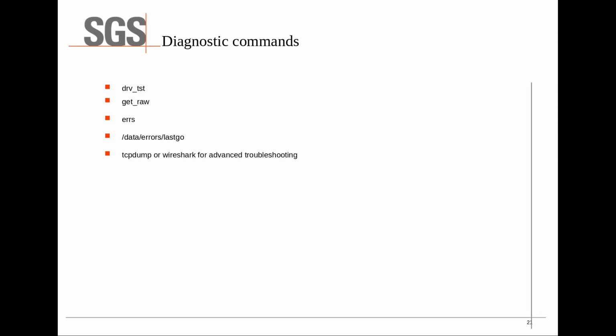Earlier we had that slide where it said we've got all these different programs: Snap IO Server, AI Attribute, AI Transfer, Build Tables, AI Specs. You could have a problem with any one of those. And we mentioned there's the different files that are configured: the Go script, the attribute file, input specs, and a calibration table. You could have an error in any one of those files. What you're trying to do is narrow down where the problem is so you know which file you need to fix.